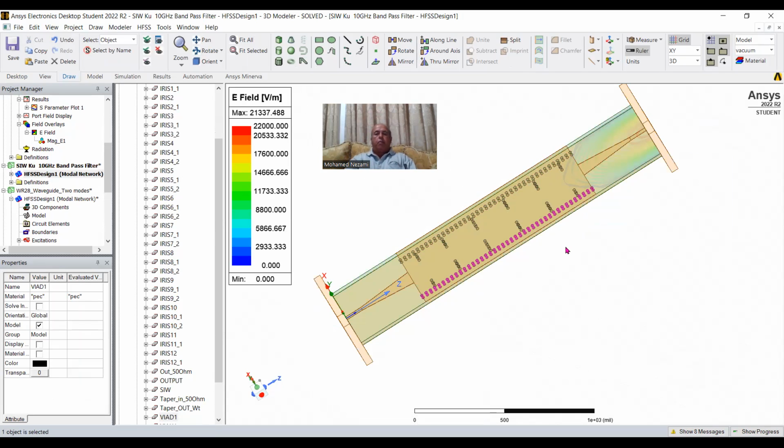And this may involve using another package like ADS or some other filter synthesis program, because you might remember from filter theory, you start out with the filter shape, the frequency response shape, and then you go on to implementing that in a transfer function, and that transfer function then gives you a bunch of G's, we call them G0, all the way to whatever polynomial length that you have for Chebyshev or Bessel or these other classes of filters.